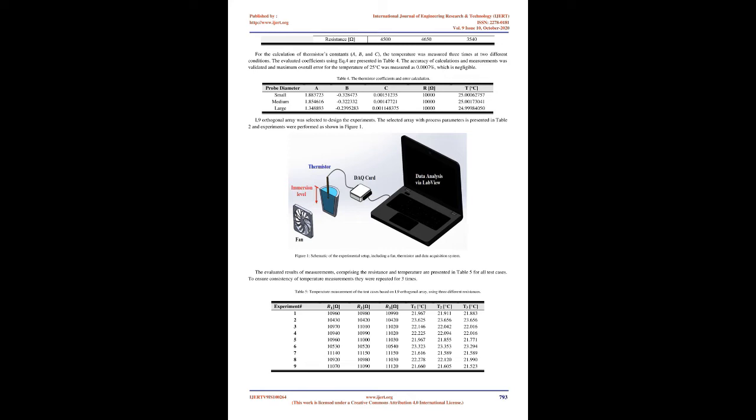2. Selection of parameters. 2.1. S/N, signal-to-noise, ratio. The main goal of the paper is to improve the quality of temperature measurement for different applications by determining the best combination of parameters and levels affecting the measurement procedure, as shown in Table 1. In this study, the significance of 4 parameters and their contributions are investigated. These parameters are the operator (1), air velocity (2), the immersion level (3), and probe diameter (4), which are considered at 3 different levels. These levels are chosen based on a wide range of real applications.